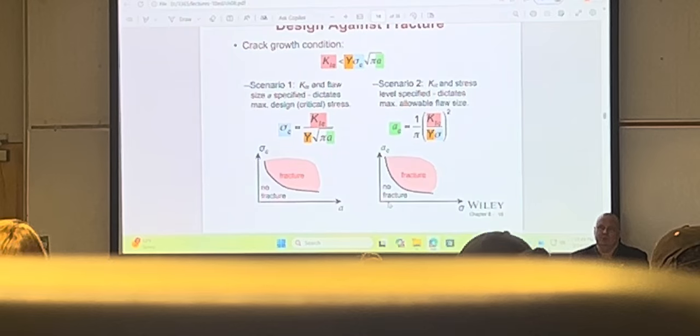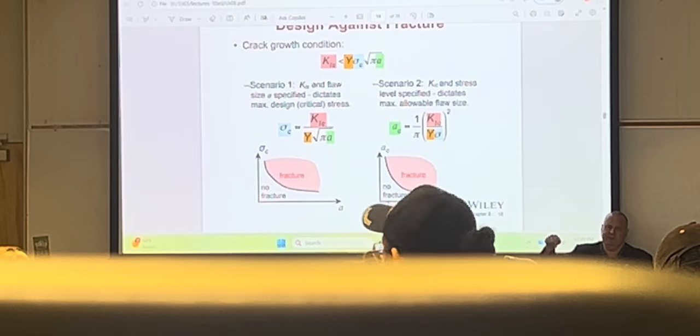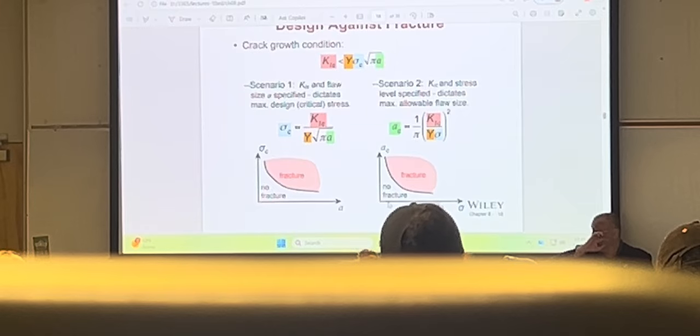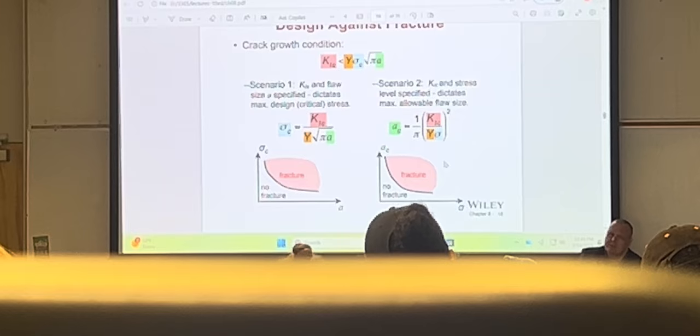So the project was to improve somehow this fracture prediction, and we had an indentation device that would test a whole bunch of those chips and measure the load at which they would fracture and analyze the statistics. So you can either measure the stress at which parts fail, or you can measure the crack length or the defect size that you would put in this equation. Does everybody understand?